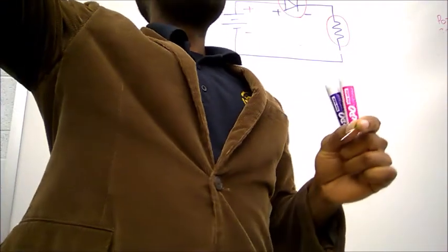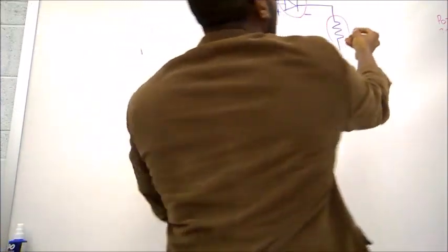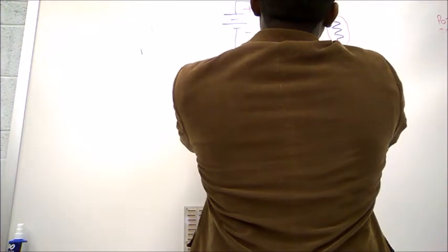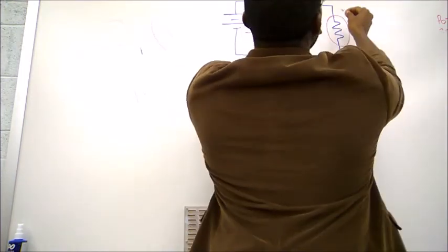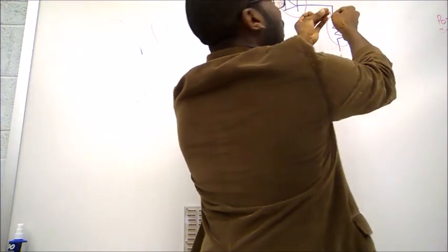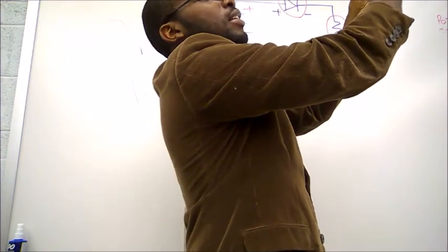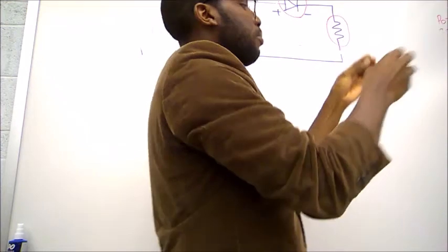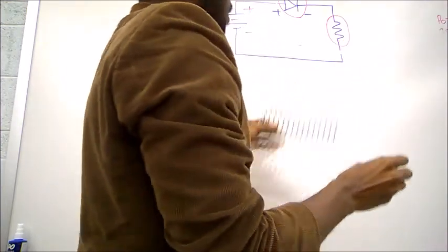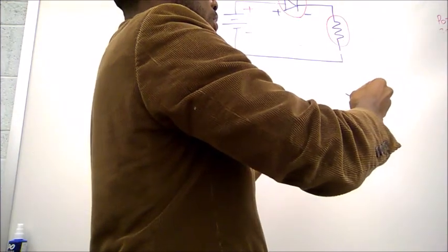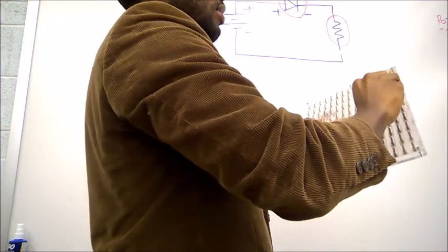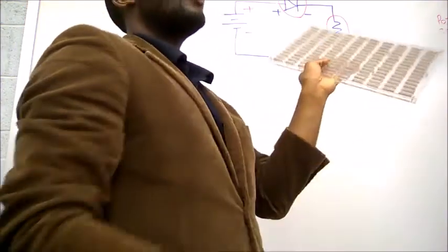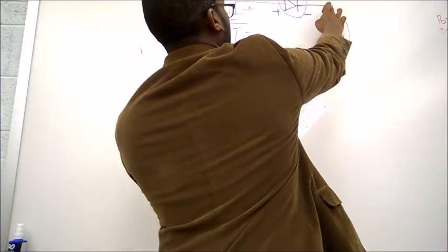2, right? So according to my circuit, I have a resistor right here, correct? And I have my LED right there, right here. And I want to connect them. To connect them, this is like a physical connection. But what we use in the lab, we use the breadboard. So if I want to connect these 2, I'm just going to put them in the same row on the breadboard, because this is just like a connector. So now the 2 of these, we have this connection done right here.